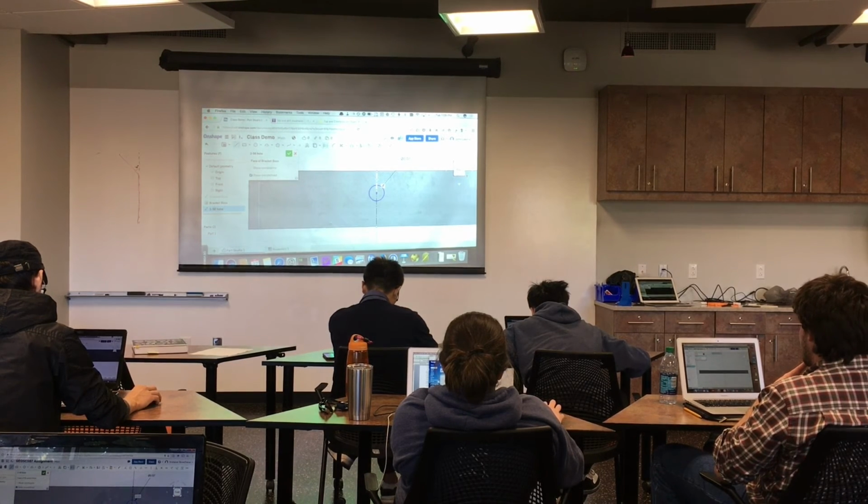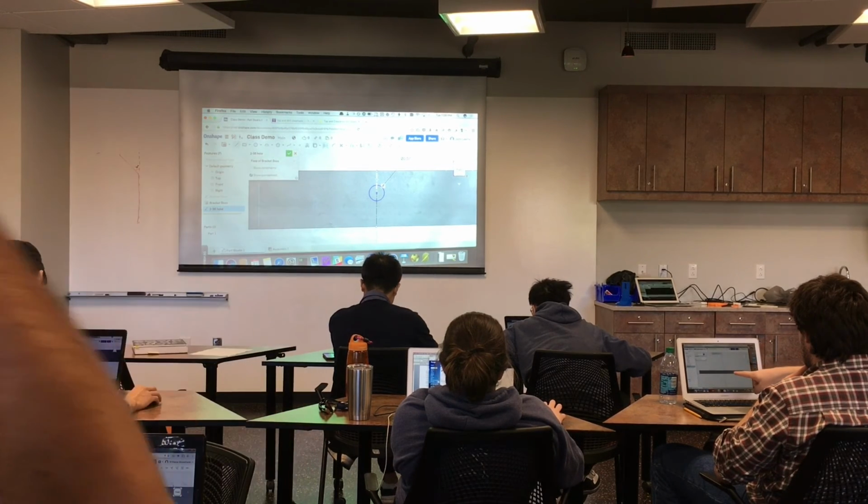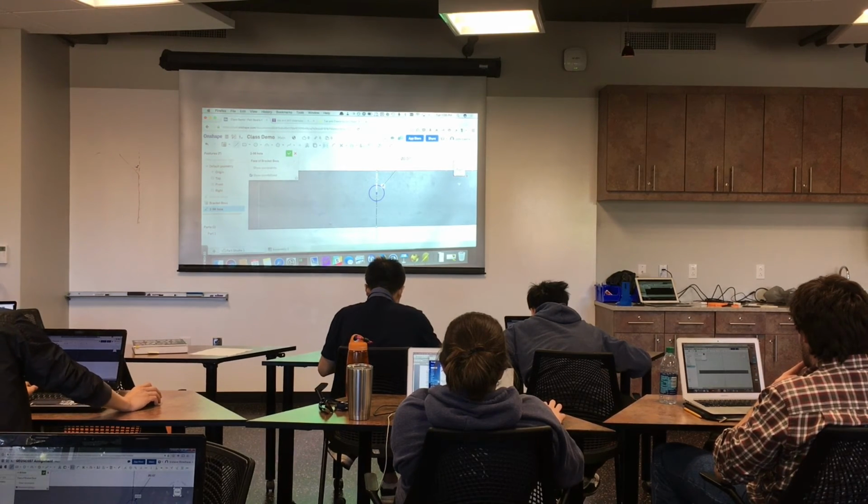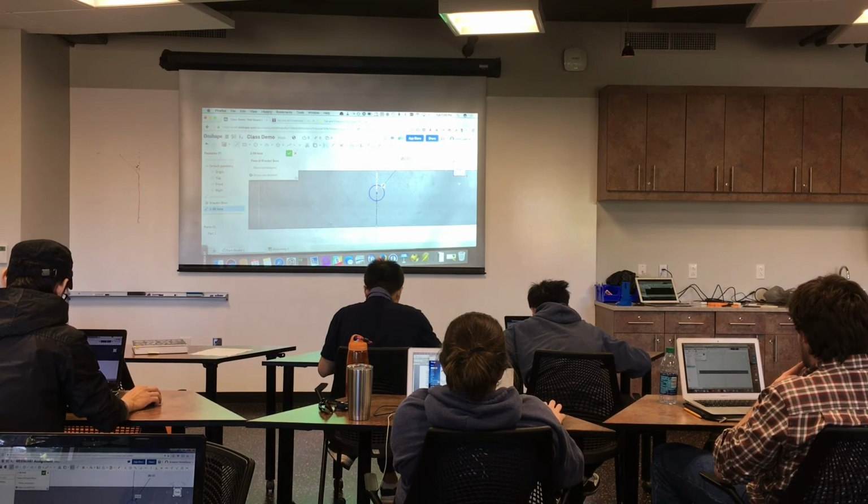Okay, what's going on? Okay, so, oh, you didn't tell it a sketch plane. So double click, click the face. Now you can add the circle. Yeah.